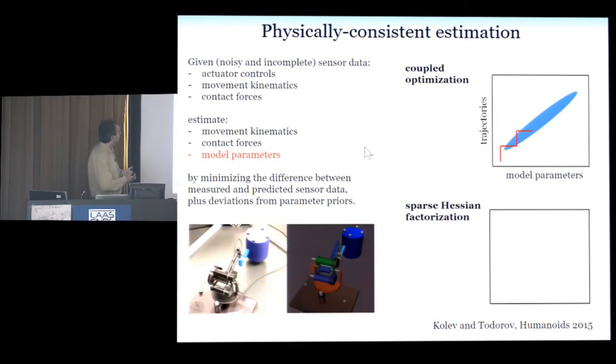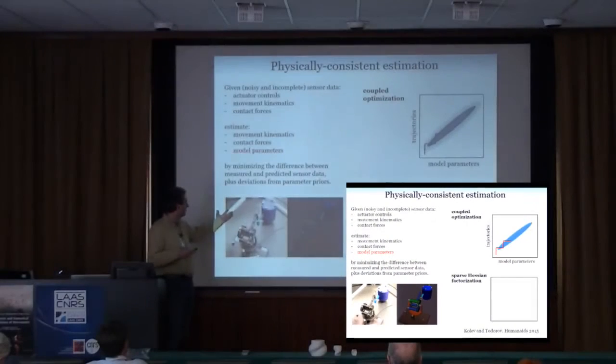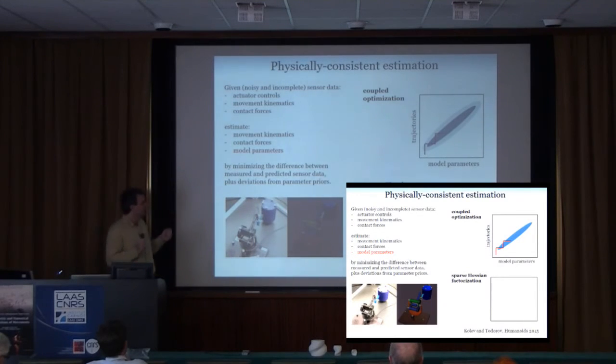Now, what we'll have to do is there are two sets of unknowns here. One is the model parameters, which are things like contact parameters that I referred to earlier, and then there are some stiffnesses in this thing, and the actual physical dimensions and such, inertias, gains on the motor system. So those are the things that we want to infer from the data, and this is called system identification. But there are also the actual motions. You don't really know what they are. I mean, you have sensors, actually very accurate sensors, but still they may not be exact. And that turns out to be a real problem here.